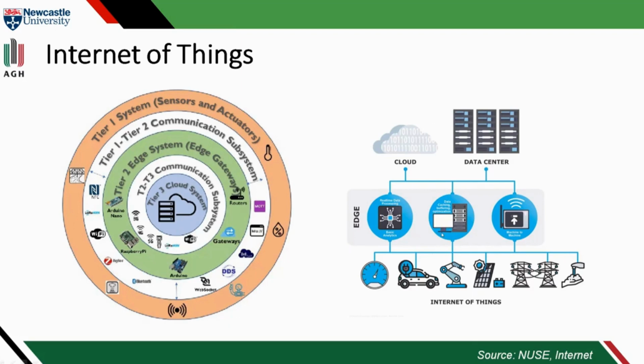of the system. Nevertheless, the problem is that this kind of solution is quite complex in architectural design from the hardware point of view, because we might have different communication technologies from IoT devices to the edge and from the edge to the cloud. So we might have technologies like Zigbee, Bluetooth connectivity, mesh networking like OpenThread for communication between the sensors and the edge devices. Then from the edge to the cloud, we might have a simple fiber connection, Wi-Fi connection, or we might have low power WAN connectivity like narrowband IoT, which is at some point unreliable for sending the data and with very low throughput. And of course, we might also have IoT devices connected directly to the cloud using narrowband IoT connectivity.